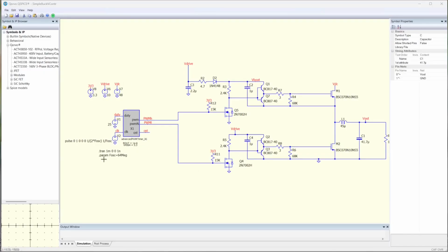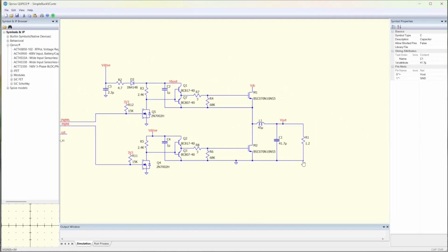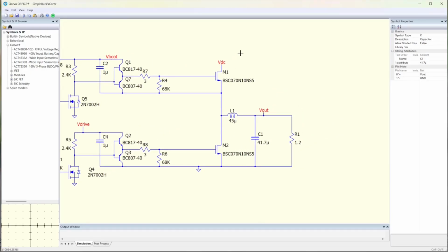Now we will simulate the buck converter with the PWM. The C block with an incorporated advanced PWM is used, which I showed exactly in a previous video. I will put a link into the description. Additionally, I used a discrete gate driver, which I also illustrated in my last video. I will put a link into the description. Now for the buck converter, it's actually just those components.